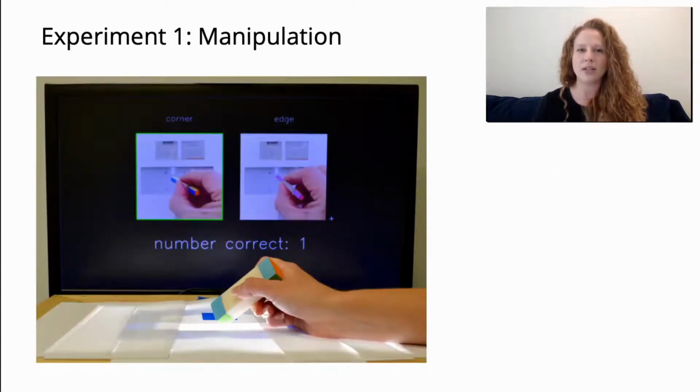So we built a light box with some light bulbs, a camera at the bottom, and a plexiglass top, and there was a resistive touch sensor on top of the plexiglass. The resistive touch sensor allowed us to know when a mock-up was touching the screen, and we used the current frame of the camera to classify which contact was touching. Now remember how we painted each side a different color? We measured the relative proportions of each color in the frame when the mock-up was touching the screen to determine which contact was touching the screen.